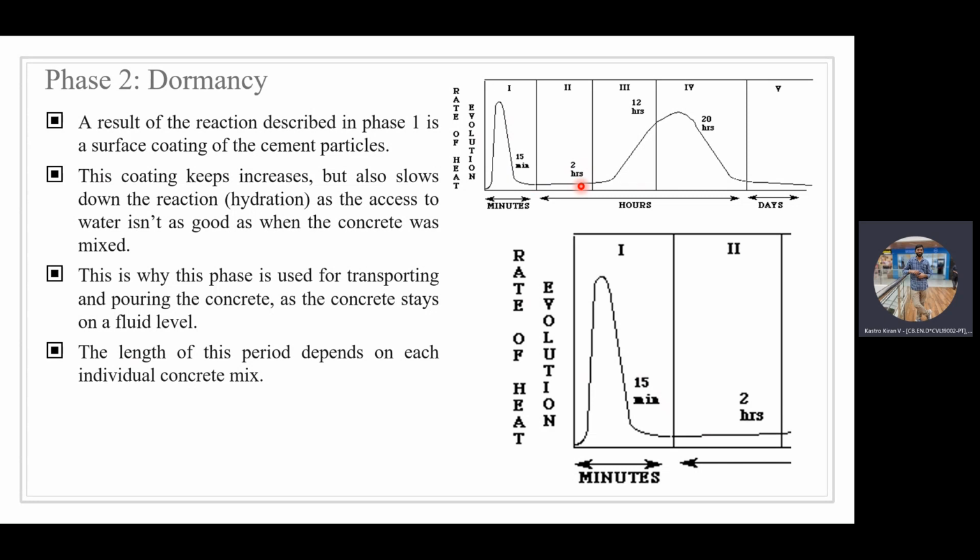Sometimes you are going to use quick setting concrete. Sometimes you are going to use rapid hardening concrete. In such cases, this period, this 2 hours of period, will get changed. And this phase basically ends with the initial setting time of concrete.